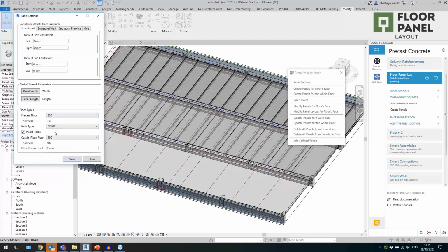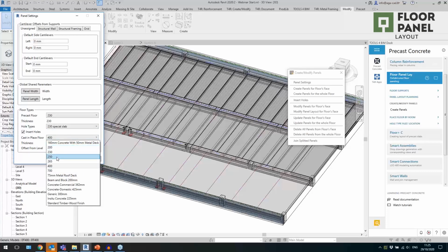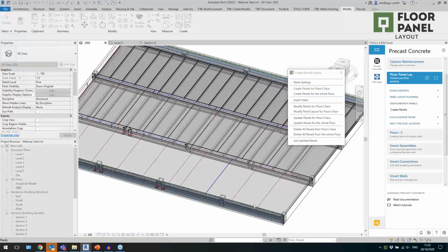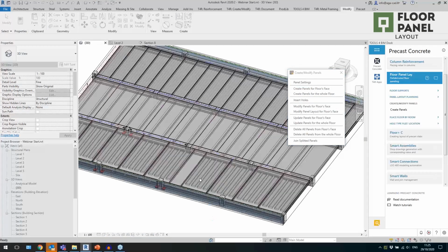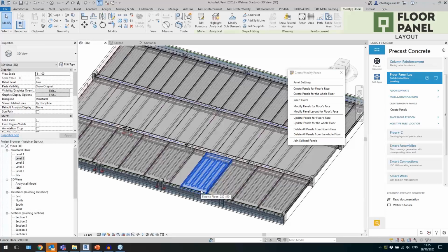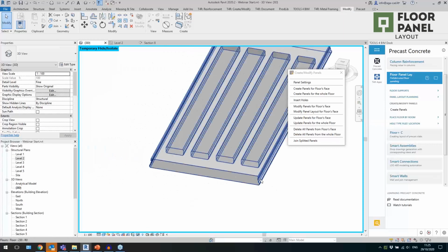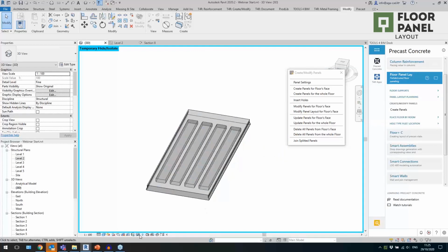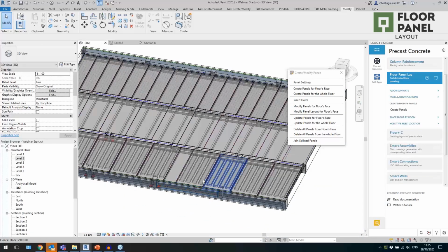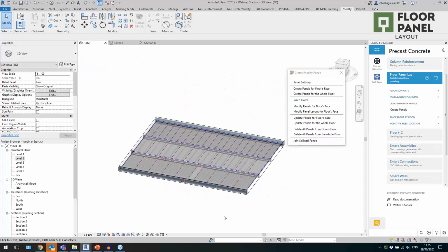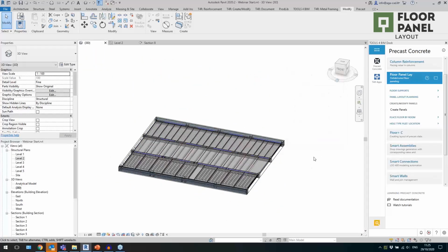And then even I can go even further, right? I can say this should be special slab cutout to get special shape of my slabs. And let's do it like that for these guys, right? So what I have here now is this kind of shape. So I have some cut out at the edges, and I also have some voids inside. So this depends on the family you use, right? So it could be quite anything you need. All right. That's the floors, what I wanted to show.